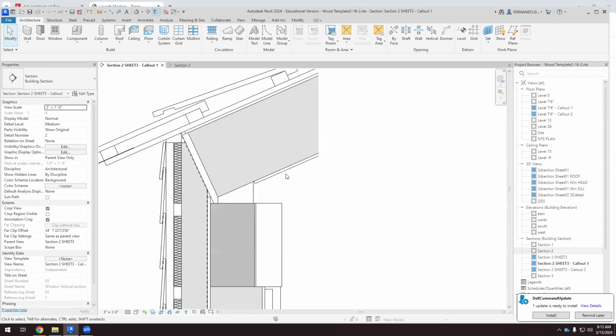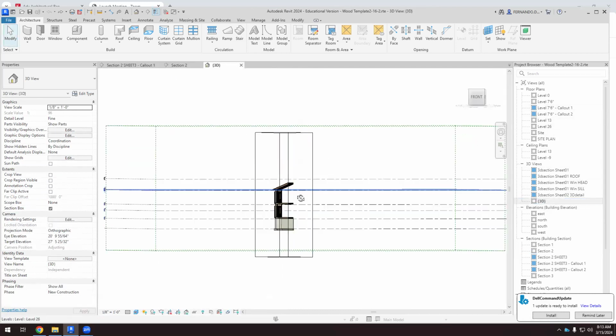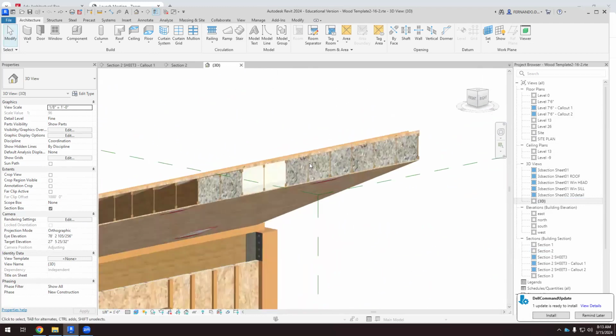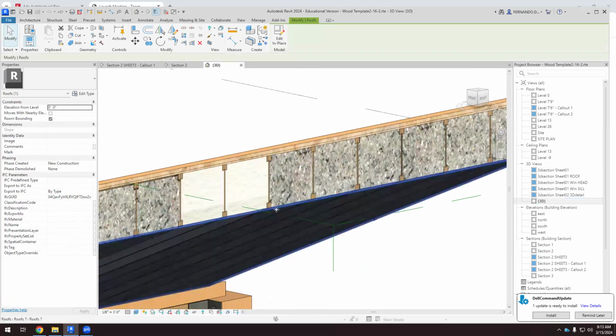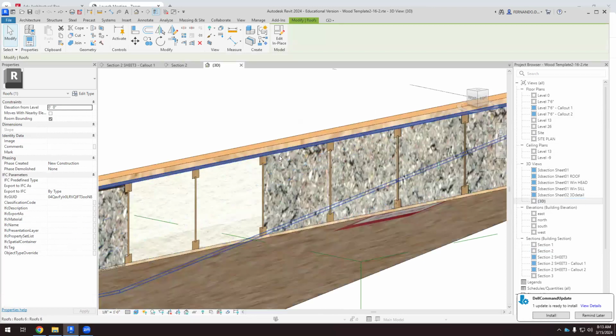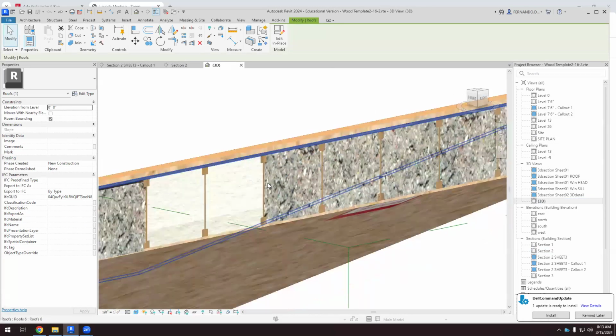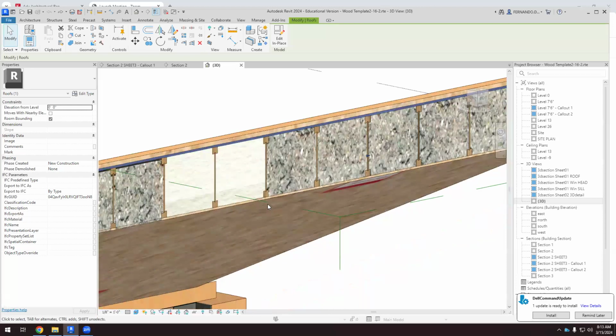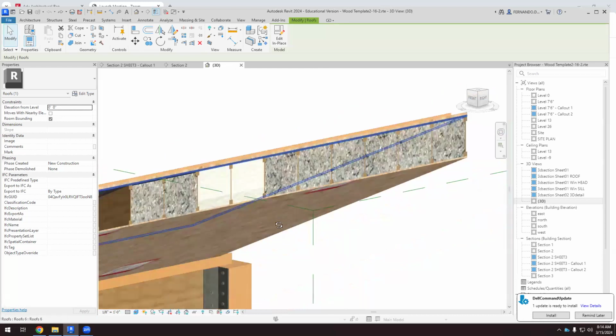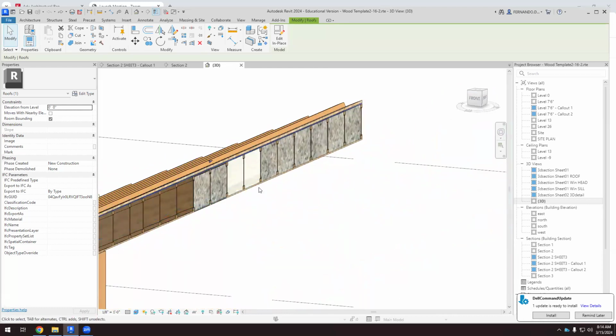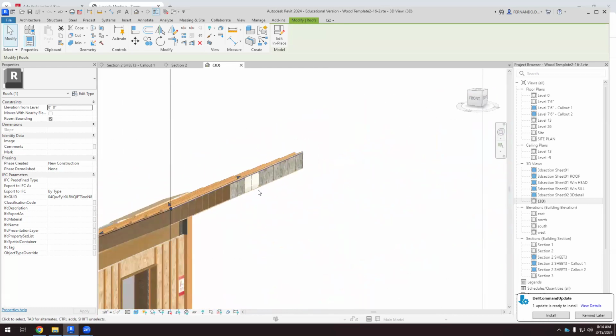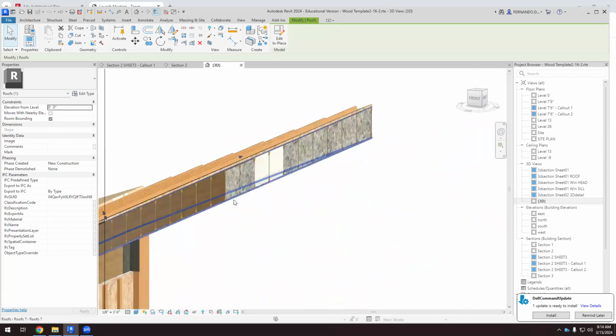So let's do that. Imagine that I have this roof. As I told you, we have this thermal breach here, okay, because we have this board, and we have the joist. So the joist can be a thermal breach. So we need to interrupt the heat flow like that. Okay, so I'm going to apply thermal insulation here at the bottom or in the interior side of this roof.